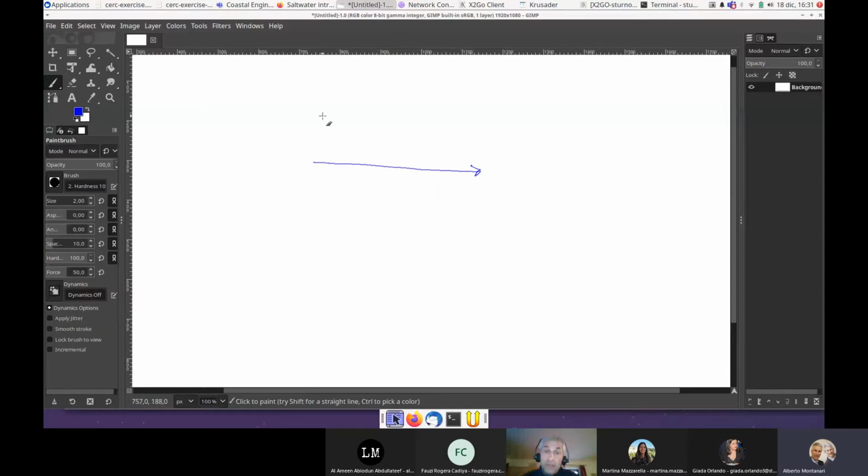So you can neglect the other two directions. And if you have a water flow in the groundwater that is taking place in a volume of groundwater soil, let's suppose that this flow is characterized by a velocity that is coming out from here, which is dominant along one direction.